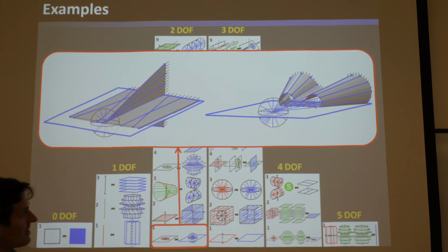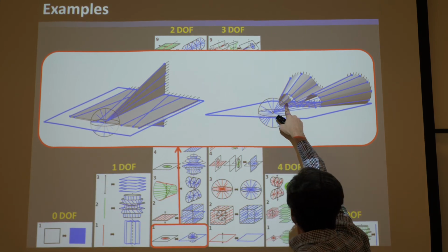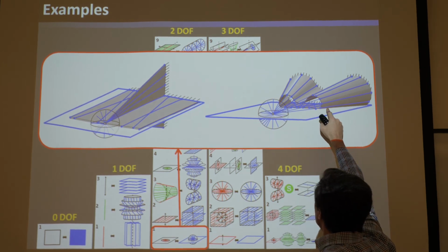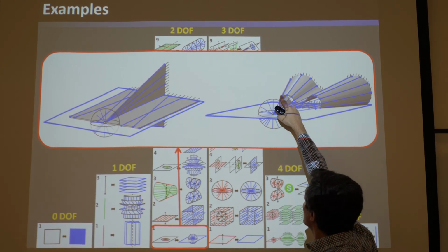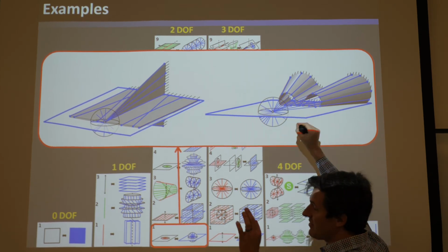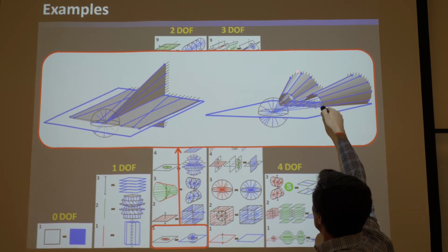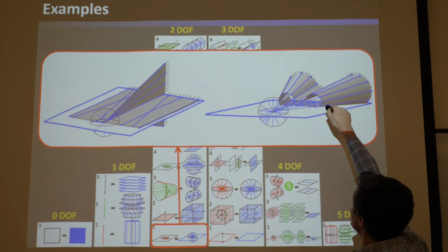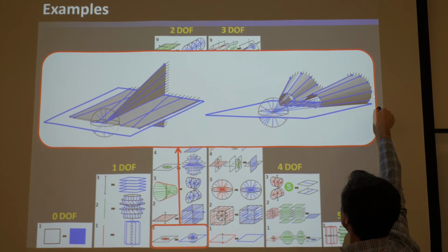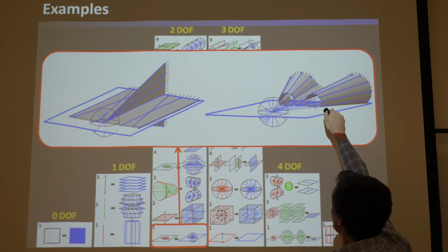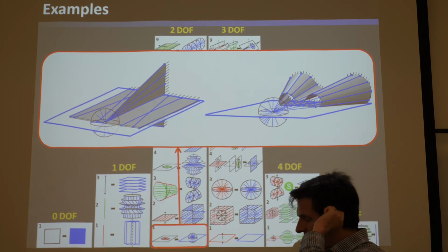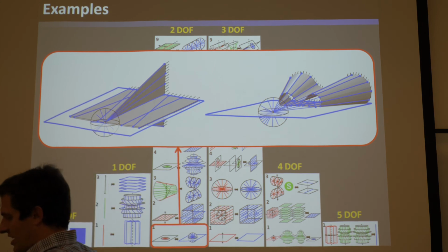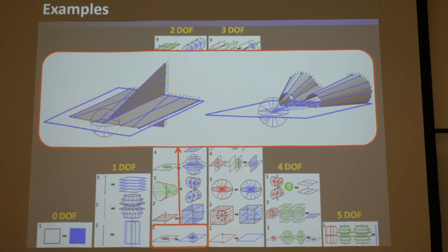And even more interestingly, look at this guy. Say this was a flat blade on this plane, but then this was some bizarre curved surface, like a hollow shell that's infinitely thin, and it just makes sure all the blue lines that lie on that satisfy the condition, where this back thatched edge is the ground and this front edge would be the stage you attach it onto. The blue lines would directly connect them, wouldn't exit the geometry, and would fill it entirely blue. So you get the disk centered right there, and that's where the freedom space would be.